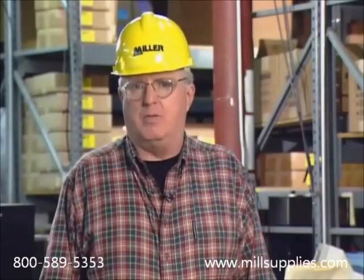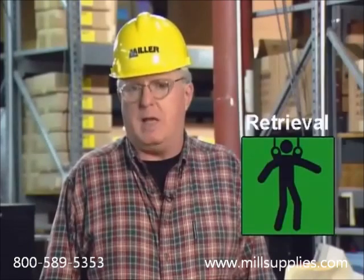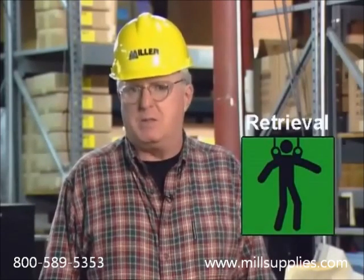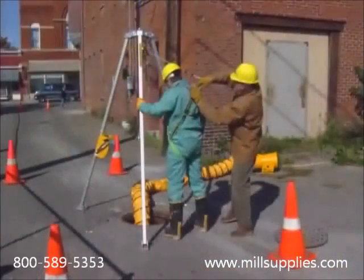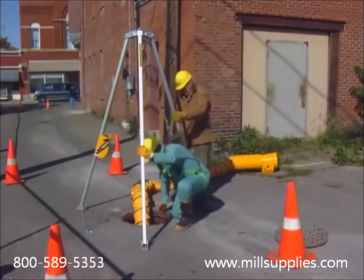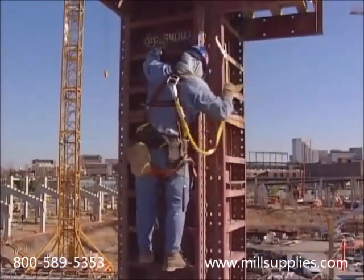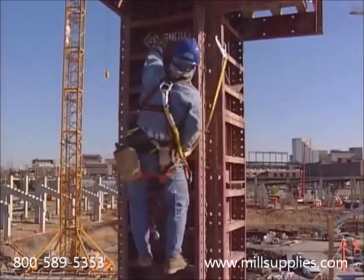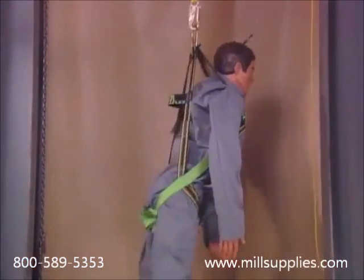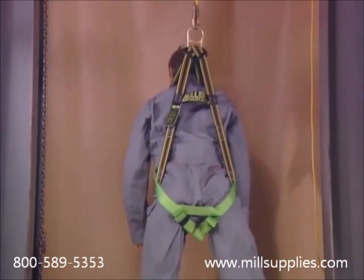The final category of fall protection products is retrieval equipment. This is generally used in applications where workers must enter tanks, manholes, and other confined spaces. A retrieval system consists of a full-body harness, a retrieval unit, and an attachment point such as a tripod. The most basic item of fall protection equipment is the full-body harness. A full-body harness distributes fall forces throughout the body, thus reducing the chance of injury.